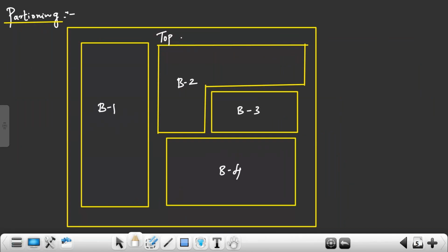But partitioning you have to do, right? Block 1, you want this much area. Block 2, if I assign this much area to block 2, then where to accommodate block 3? To accommodate block 3 here, block 2 should go with this shape. You should just guide the tool: okay, let block 2 be in the inverted L shape, and block 3 I will fit here. So the tool will help you. The tool will do all these things. You just guide the tool.